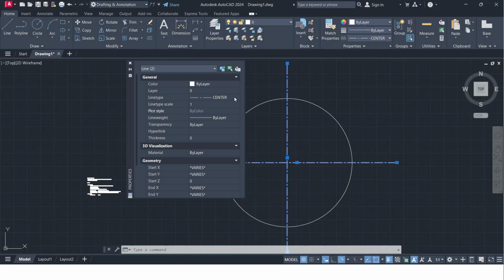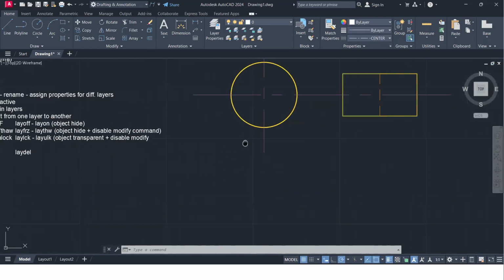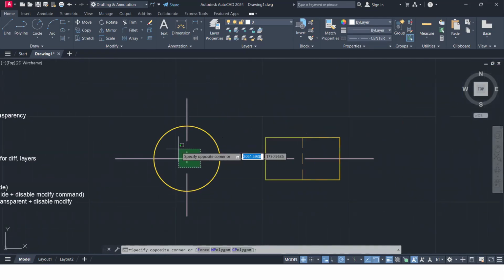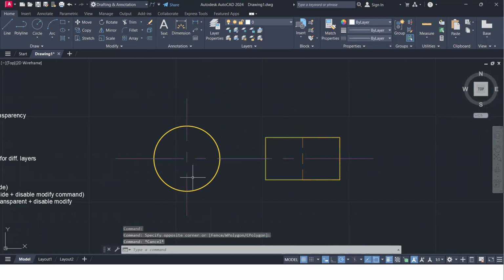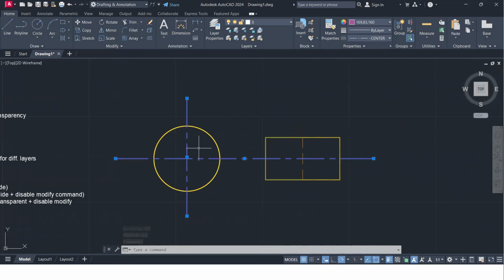And then which type of line do you use? Center line, and you can also change it this way, okay? Because here we load this line. First of all, load the line type, whichever line you want, and after this you can use it. This way you can use the line, okay? And then suppose here I want to show this line in PR, right? And then I want to set a small dash scaling because I want to show it in a better way. So I use 0.5 here for better showing.